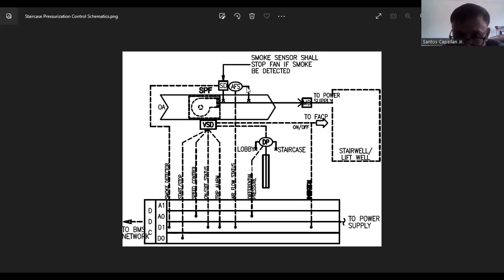Okay. This airflow switch, as you can see, has one probe going to the supply discharge of the fan. Then on the discharge side of the fan, I think one of the probes is exposed to atmosphere. So basically, if there are two probes, one should be inside the other. The negative probe should be inserted at the suction side of the fan. Okay, so anyway, again, this airflow switch, this is a monitoring point, where should it fall?